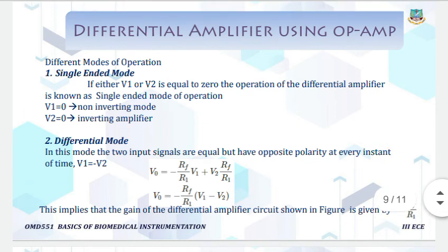Next one is the differential mode. In this mode, there is a differential between the two signals. The two input signals are equal but have opposite polarity. Suppose we take V1 as positive, then V2 is negative.